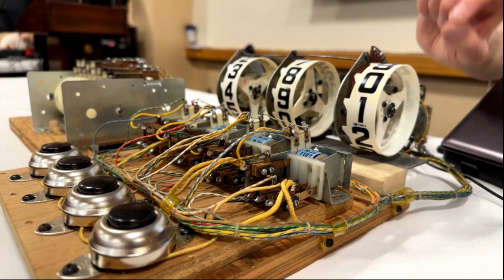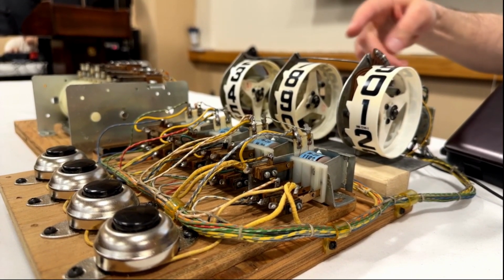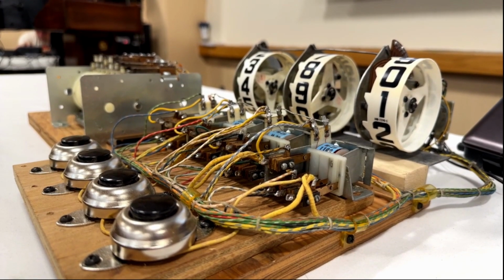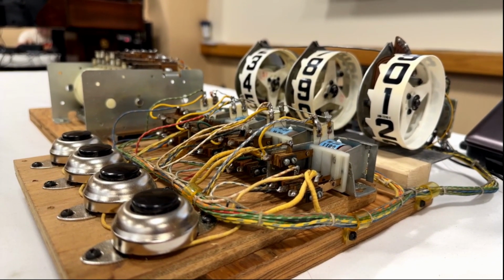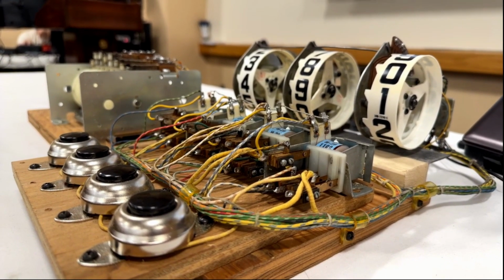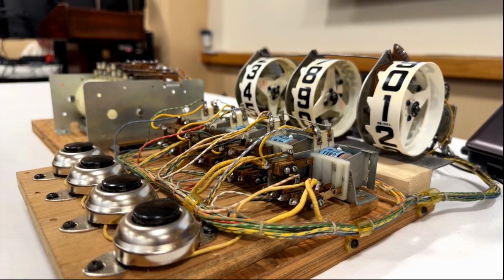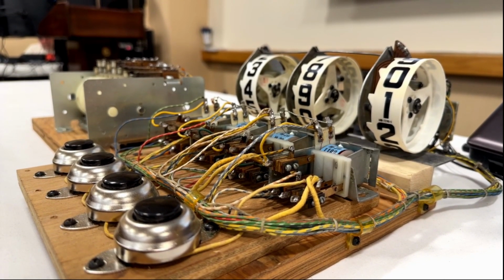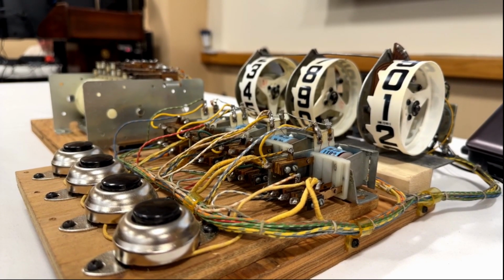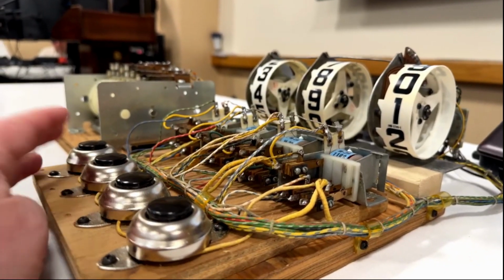So their 0 position switches are all going to change at different times as this motor is running, and they will stop independently. Question? And that is because you shut off the carryover circuit, so you don't have to worry about if you gave extra pulses to the 10s because of the carryover. Yes, the carryover, I sort of simplified that circuit a little bit. The carryover circuit is smart enough to recognize that I shouldn't be doing this if we're resetting. So there's another switch that I did not demonstrate that makes these circuits exclusive. Okay, so go ahead and hit that last button.